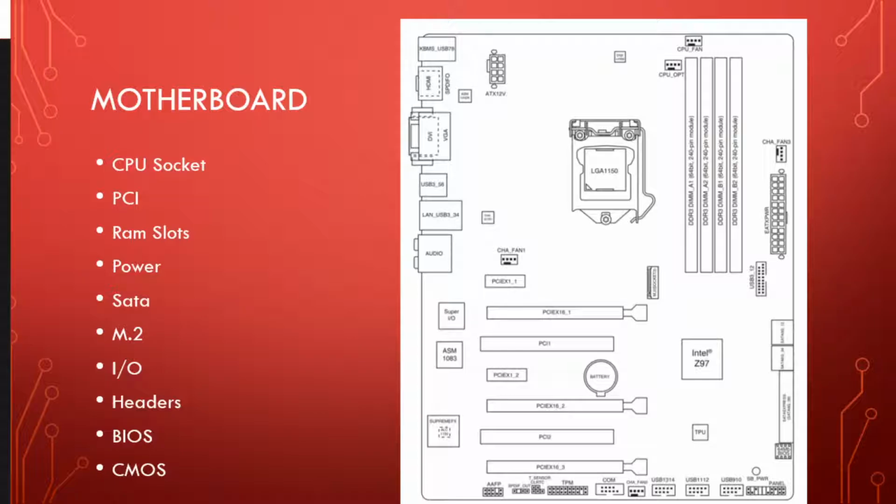You're going to have some sort of power connector on here. Basically, every motherboard for a desktop nowadays has a 24-pin connector, and some of them have another 4 or 8, or maybe dual 8s, for extra power for that CPU. Especially Intel, since they're so power hungry, they're going to have another wire coming over to get more power to the CPU slot alone.